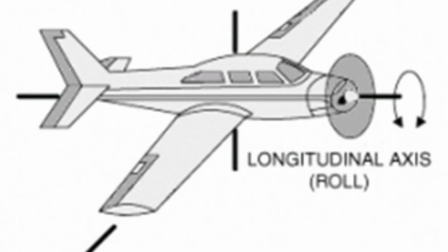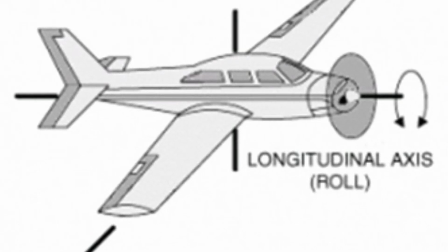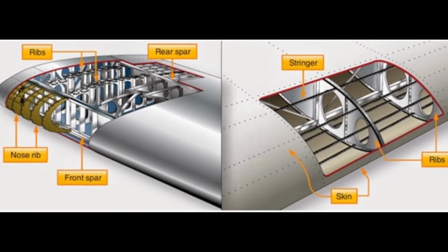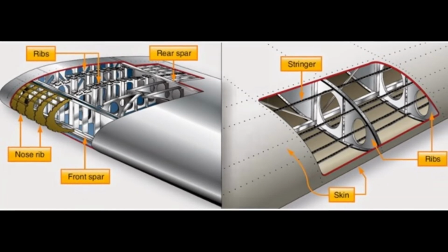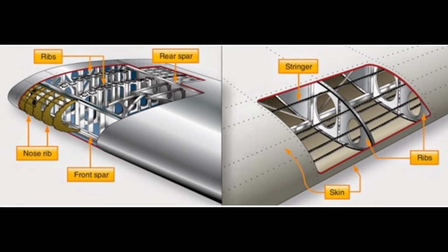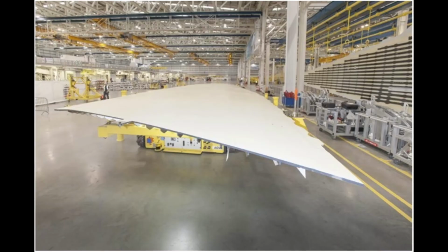Composites are made of fiber material infused within a resin matrix. Composites are lighter than aluminum and can be tailored more specifically to meet the requirements of the part they are to be used for. However, they are more expensive and complex to produce. They can cost more than 60 times more per pound, compared to aluminum.